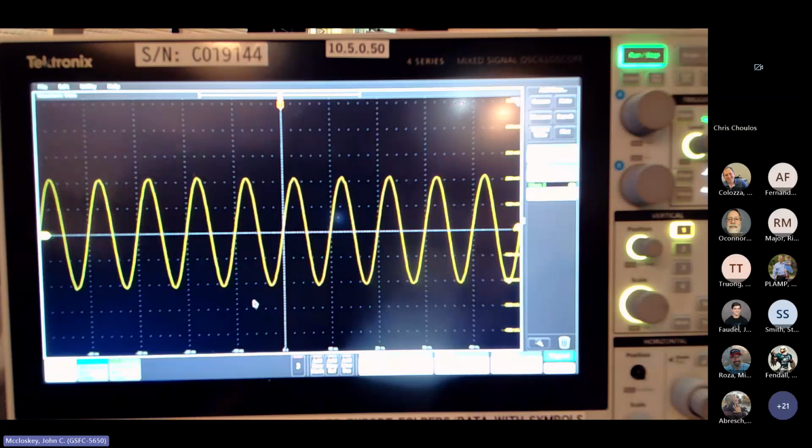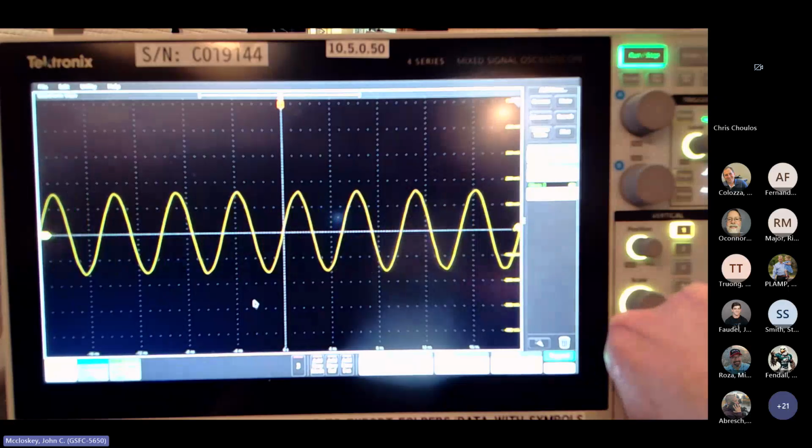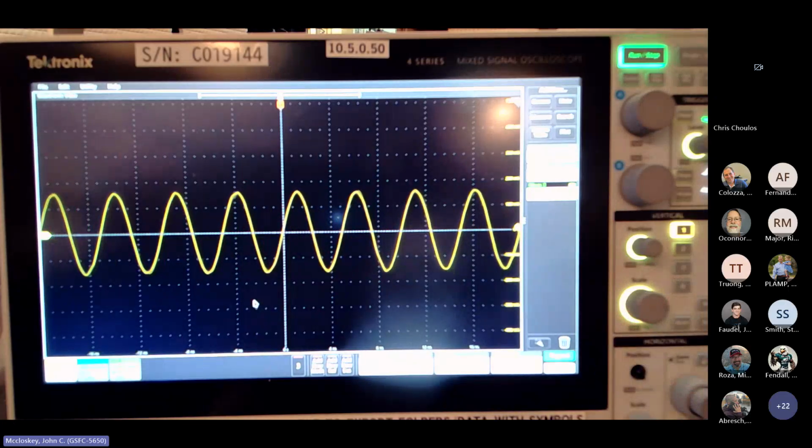We'll just call that 150, like 146. So that was our target. Actually, now we're closer to the 150. Right. Okay. So 150, 149 and change, was 146.4 on Monday. And the last one will be 200 megahertz. This is the high end of the frequency range. Okay. Now it starts to decrease a little bit. You're getting some additional losses and parasitics. But now we're about at 110 millivolts RMS, 106.4 the other day.